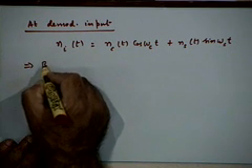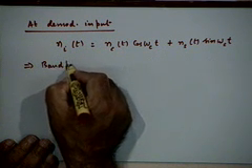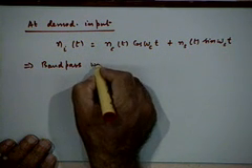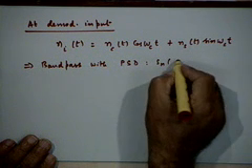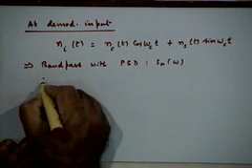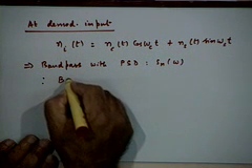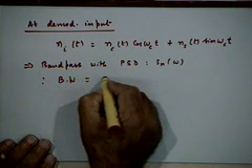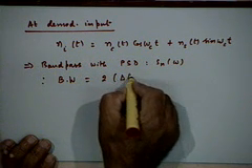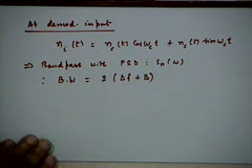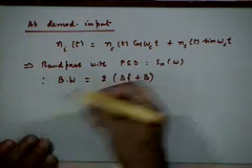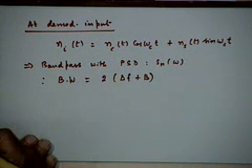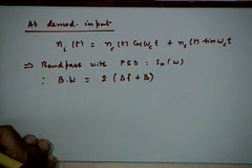So, it is a band pass process with a power spectral density function, which we can denote by S_n(omega). The important thing is that this power spectral density function will have a bandwidth which is equal to 2(delta f plus B), isn't it? Carson's rule. The delta f is the peak frequency deviation of your modulator, whether it is FM modulator or PM modulator, right.